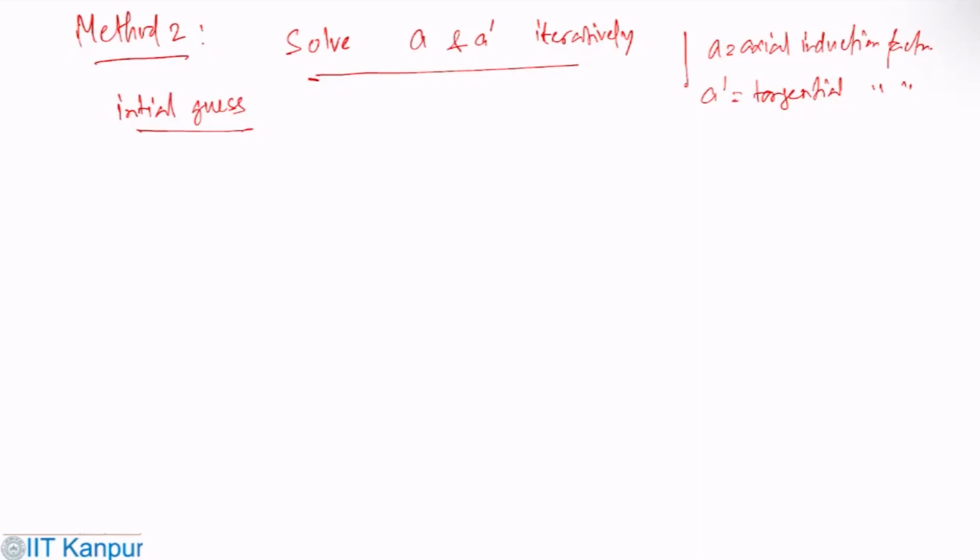So importantly, what is required is that we start with an initial guess, and these guesses can be values from, as I said, the adjacent blade section. This could be from a previous design in the iterative rotor design process. That could be method one, or use an estimate based on the design values from optimum blade design.